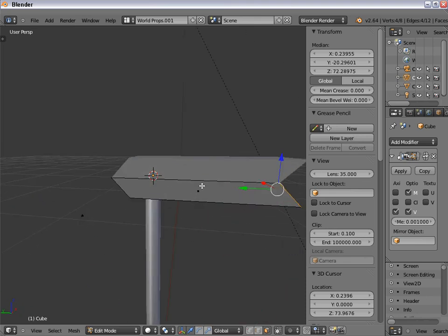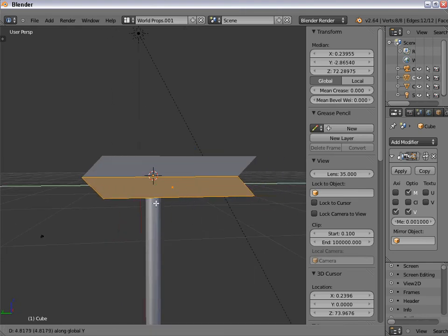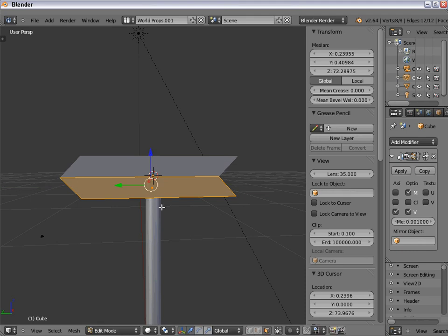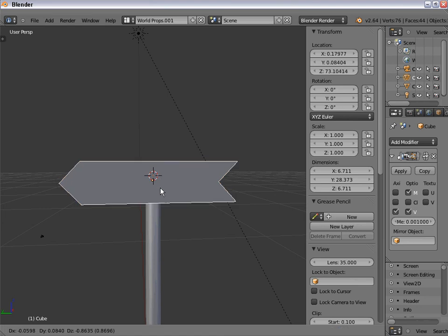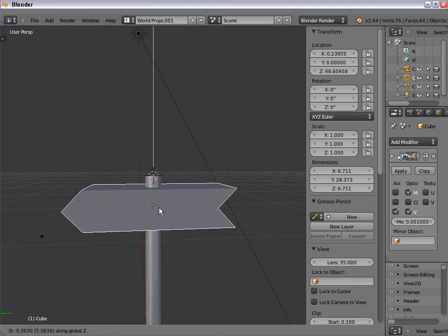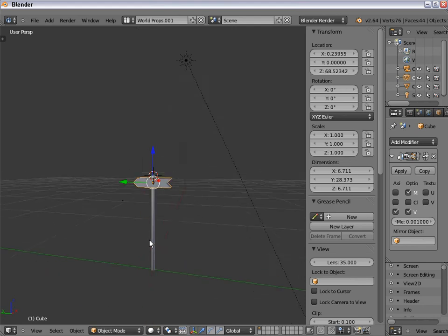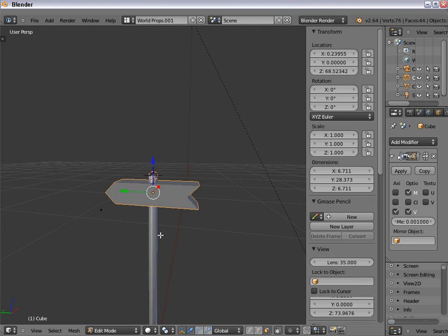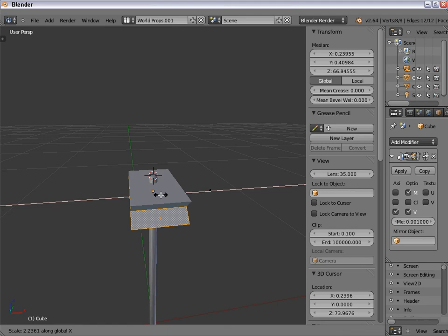Now I will select all of the faces and I will drag this to the left a bit more from this viewport. I'll drag down in object mode so that we move the mesh and its deformed modifier counterpart. Okay, that looks about right. Now the thickness, I'll simply scale on the x-axis. In fact, I'll type this scale in.